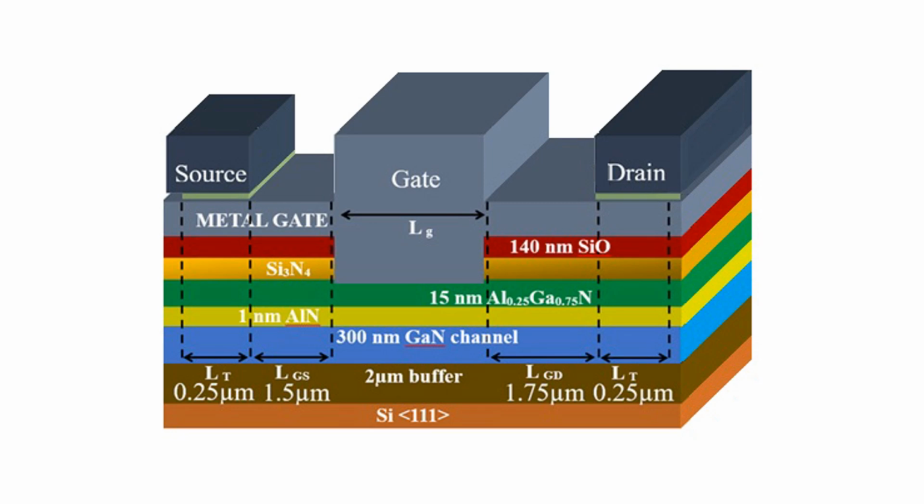This work compares 4 widely used threshold voltage extraction methods in high-mobility electron field effect transistors fabricated at IMEC. Here it is demonstrated that linear extrapolation provides the most robust threshold voltage definition across different geometries and bias conditions. By normalizing drain current by gate voltage curves using VGT, it is shown that the apparent dependence on geometry discrepancies collapses, enabling a clear interpretation of aspect ratio effects under varying drain bias. These results suggest that geometry-dependent trends reported in the literature may partially arise from inconsistencies in VTH extraction, rather than intrinsic device physics.